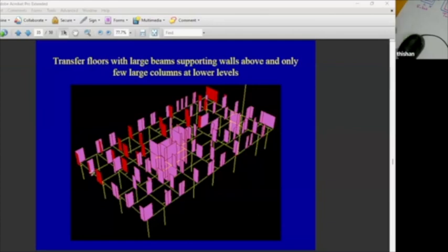So in that context, we have to make sure we don't add additional masses and additional weight just because we are going to create a mathematical model with extra members. This is a mathematical model with extra members. Because in the actual structure, the member is so large we can support the wall directly on the member. But on the model, the width of the lines is almost zero, so we can't give any width to the large members.